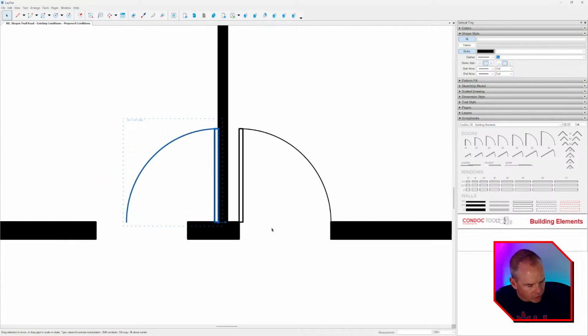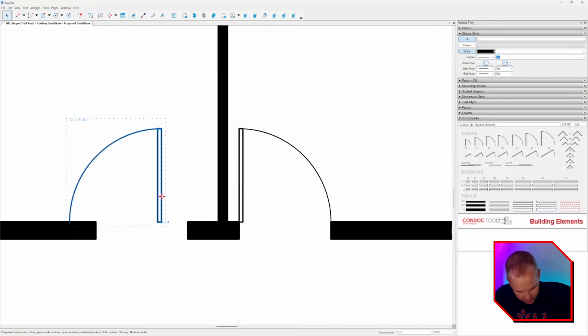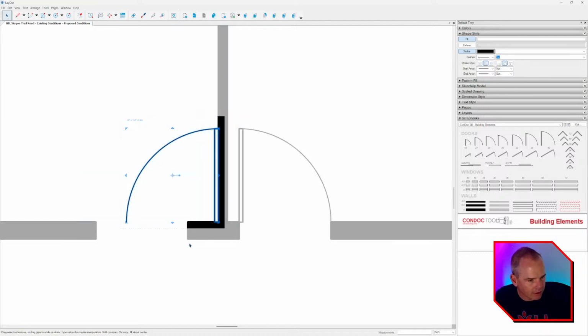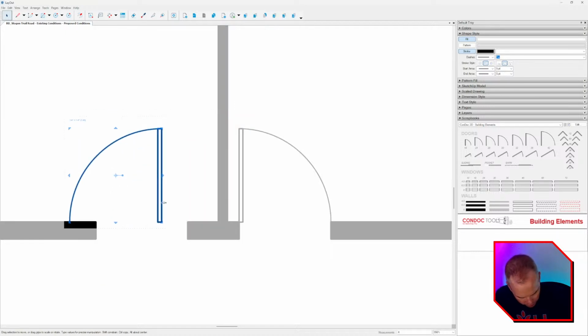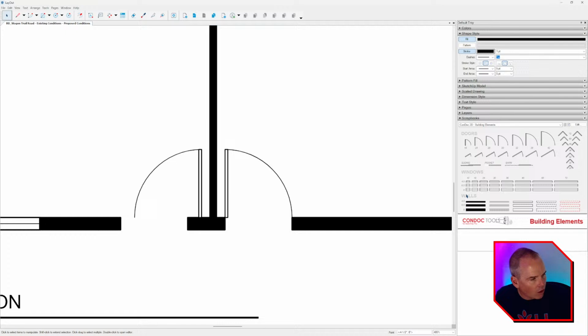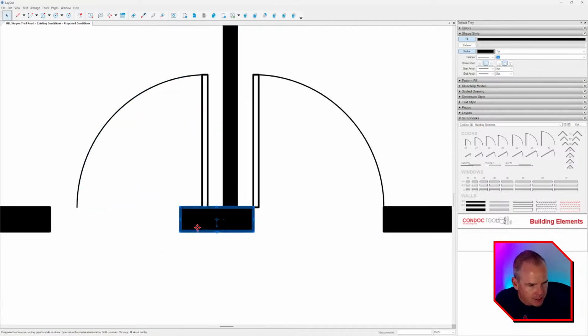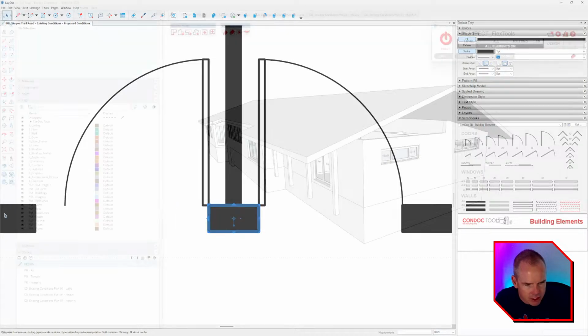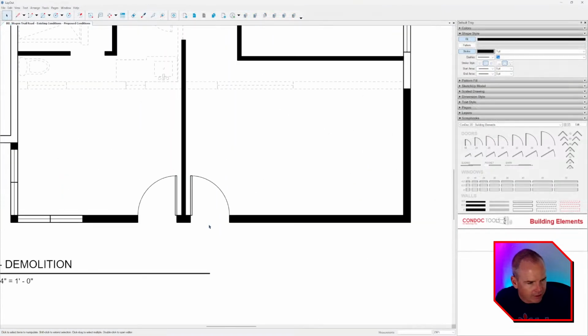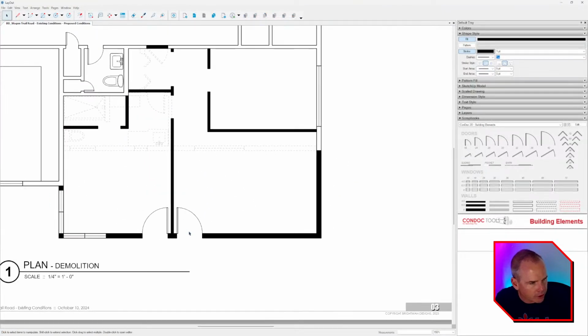So we could scoot that over and then do our 4.5 again. So this one I need to double click in and then move it 4.5 inches, enter. All these scrapbooks over here, these are all scale drawings. So if you double click in, you're working at a 1/4 inch, whereas if you're out here, you're working on paper space. But no big deal. We can just snap to what we got like that. So that looks pretty good.